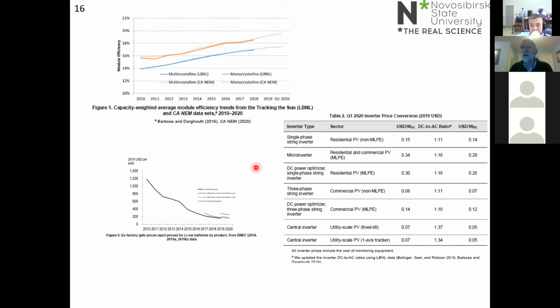There's a process called maximum power point tracking. I should have noted it down on this slide. Whereby the power electronics that is running the photovoltaic system or the wind turbine system, besides doing the conversion to good quality AC power, also has to ensure that the photovoltaics or the wind power are operating at the maximum possible efficiency point.